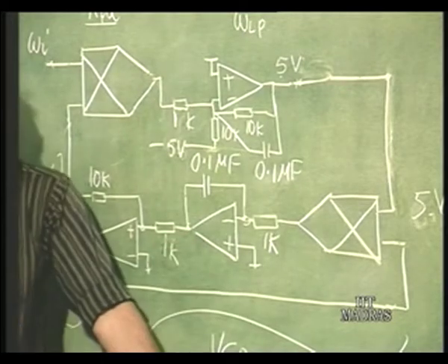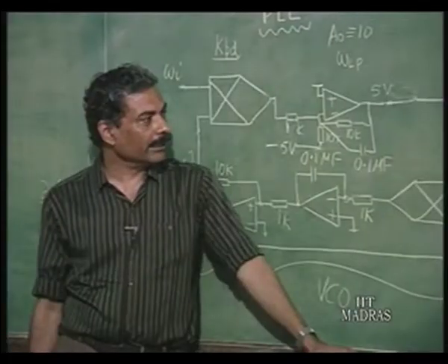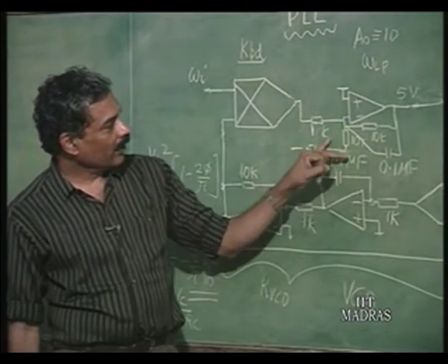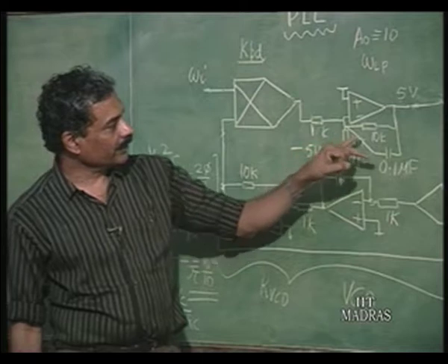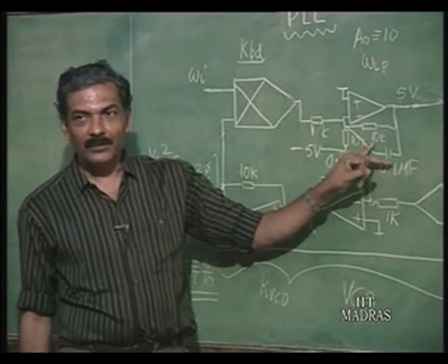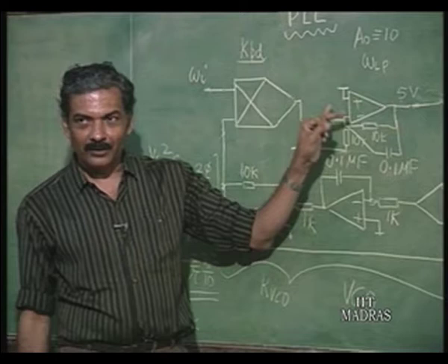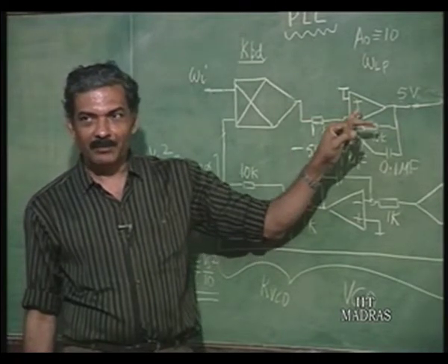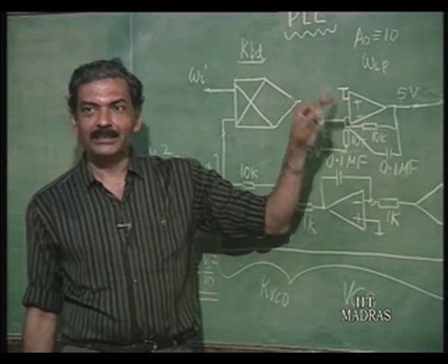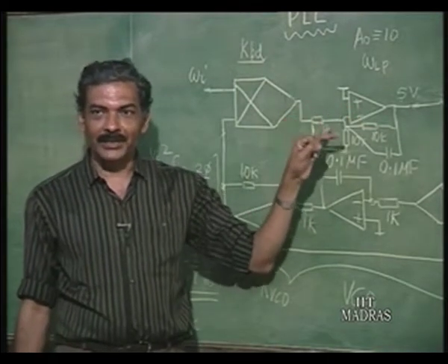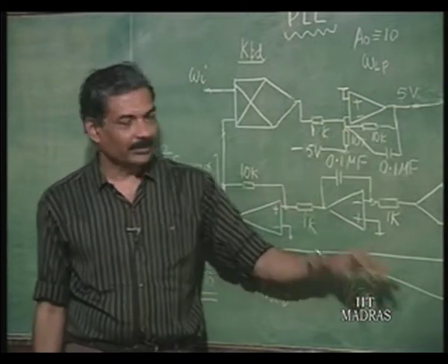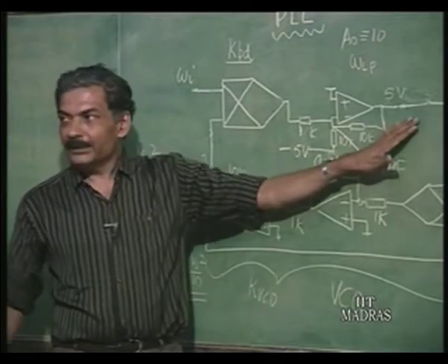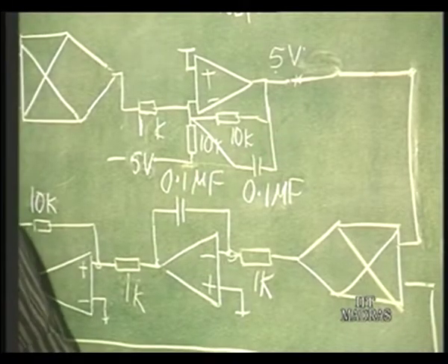something like that. So, this particular thing, in fact it is gain is 10, but strictly speaking the ratio of the resistance is 10, and therefore, the non inverting amplifier gain is 11, and therefore, the gain bandwidth product will be 1 megahertz divided by 11, not by 10. This is something that you have to note. This particular situation is depicted now in the demonstration very clearly.